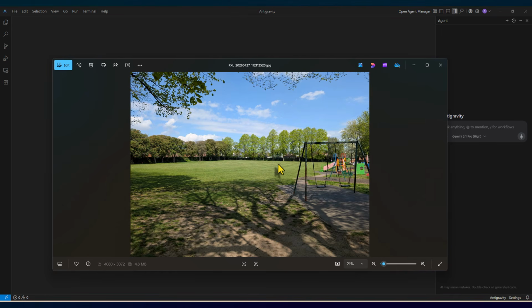So the idea is that we'd essentially use the script to select some images taken with a phone, and then the script will create points in n4ce, attach a suitable attribute to those points, which will then tell n4ce how to orientate a symbol, and then we'll automatically attach the image to it.